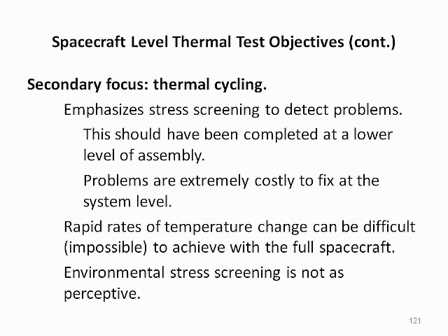A secondary focus of spacecraft level thermal testing is thermal cycling, which emphasizes stress screening to detect manufacturing workmanship problems. Ideally, most of this screening would have been accomplished through a thorough test program at a lower level of assembly, such as at the unit level. This is because problems are extremely costly to fix once a program reaches system-level tests, which is typically on the critical schedule path. Testing at the spacecraft level is also less effective because the rapid rates of temperature change needed to force a defect to become visible can be difficult or impossible to achieve with a full spacecraft.